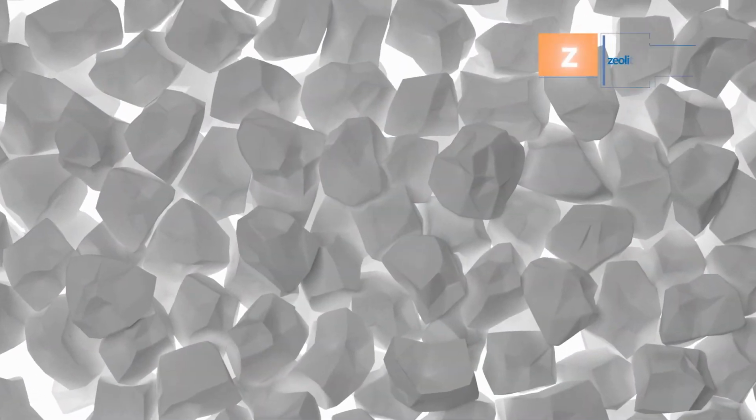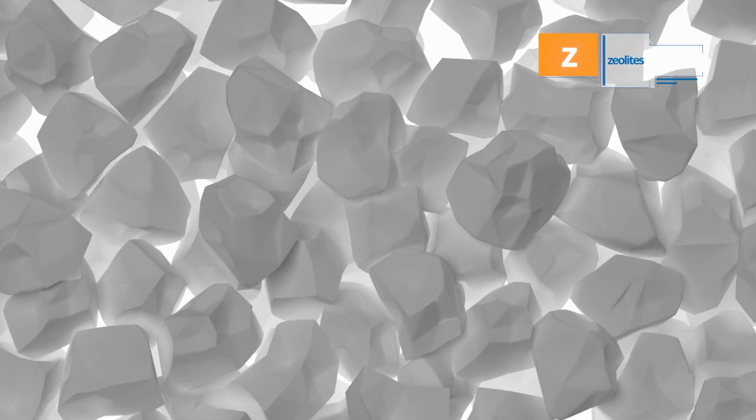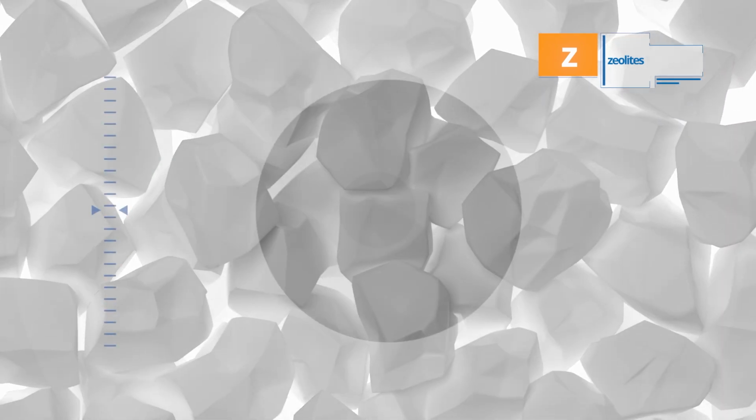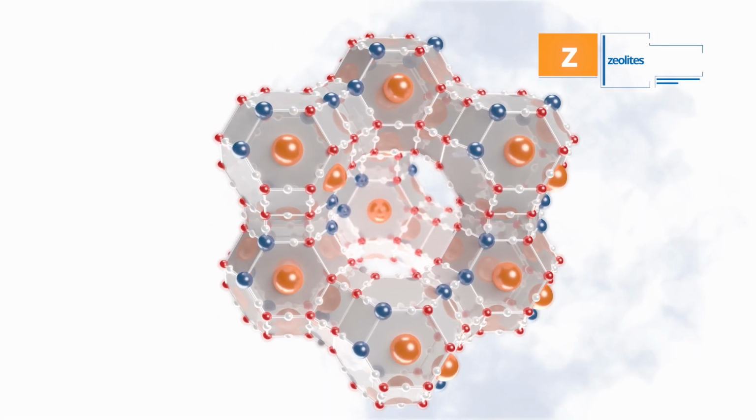Zeolite is the key and most expensive component of the FCC catalyst. It exerts the main effect on the catalyst activity and thermostability, and accordingly on product yield and selectivity. Modern catalytic cracking catalysts use synthetically produced faujasite-type zeolite Y. Zeolites are crystalline silica aluminates.